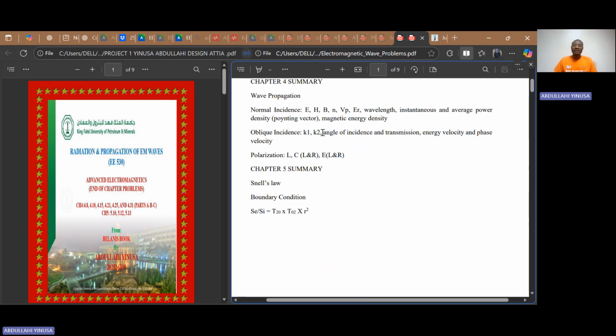If the x-axis leads the y-axis by 90, the wave is going to move in a clockwise direction. In that case, it is said to be right circular polarization. That is the sense of rotation, right circular. However, when the x-axis, known as our vertical axis, is lagging the phase of the second wave, then it is going to be left polarization, and the sense of rotation is going to be in the anti-clockwise direction.